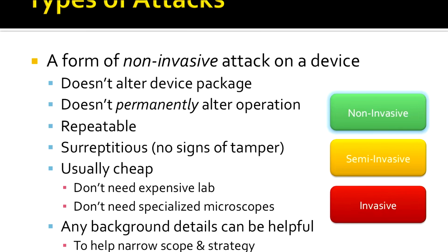If we focus on the right-hand side there on non-invasive, semi-invasive, and invasive types, electrical glitching would be considered a form of non-invasive attack on a device. This doesn't permanently alter the device's package, the physical epoxy black part of the chip. It doesn't permanently alter operation of the device, so when you stop glitching, it should work normally again. And it's repeatable, which means you can start glitching, stop, go away for a little while, come back and do it again, and it's not going to harm the device, and you can keep repeating it.